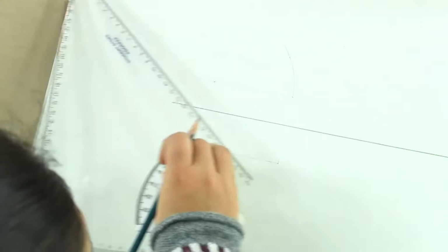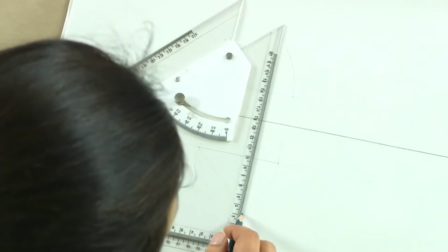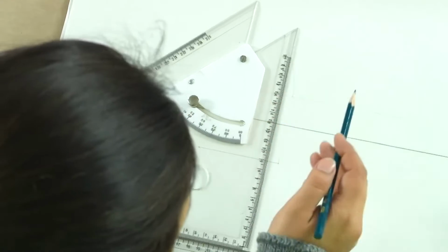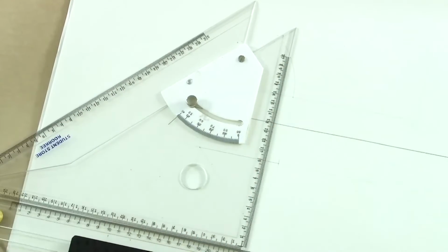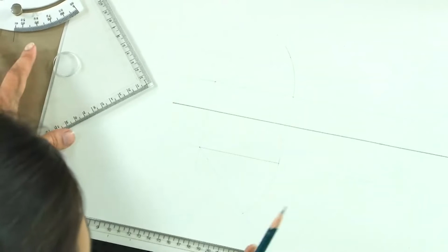We are drawing it simultaneously, but this is not how it is going to be seen, because if you take the projections up like this, you will see that it does not match with the projection of this line here. So it is absolutely not possible. These lines always have to have the same projections.